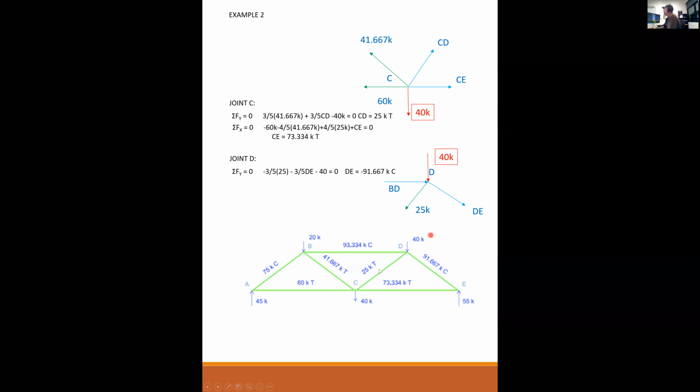And that's true for all the truss members, because as you notice, there's no loading applied on the members themselves. That's the definition of a true truss. The loads are always applied at the nodes. So all of these forces are constant from one end to the other of each one of these members. Every member has a different load, but the load in the member is constant over the length of that member.